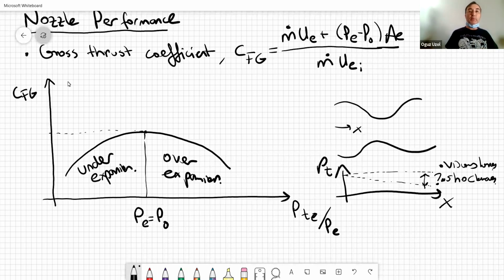But one thing that we need to be careful about, I forgot to tell you, is that let's say we started the nozzle and reached its operating design condition, so there are no shock waves. However, there will be boundary layers, but the flow potentially can separate in the diverging section from these walls. If this geometry changes very quickly, you may end up with flow separation near the walls. That will, of course, add up to big viscous loss. You don't want that. But in any case, generally, when we are designing, we try to be careful enough.